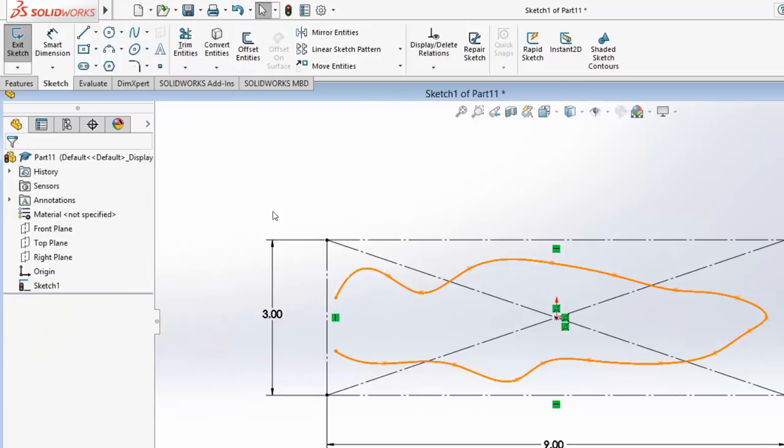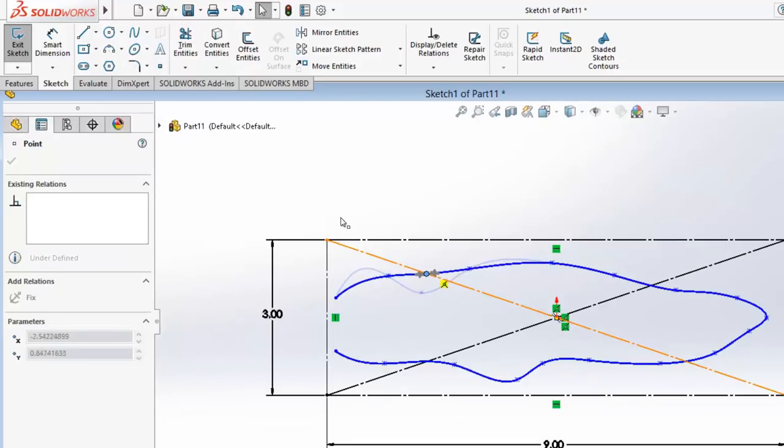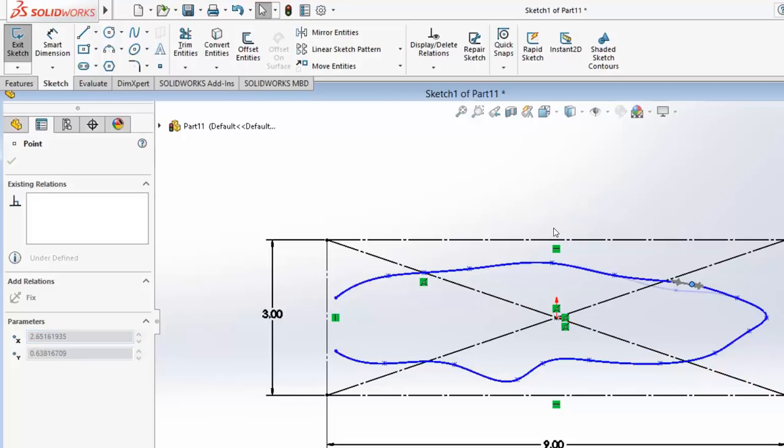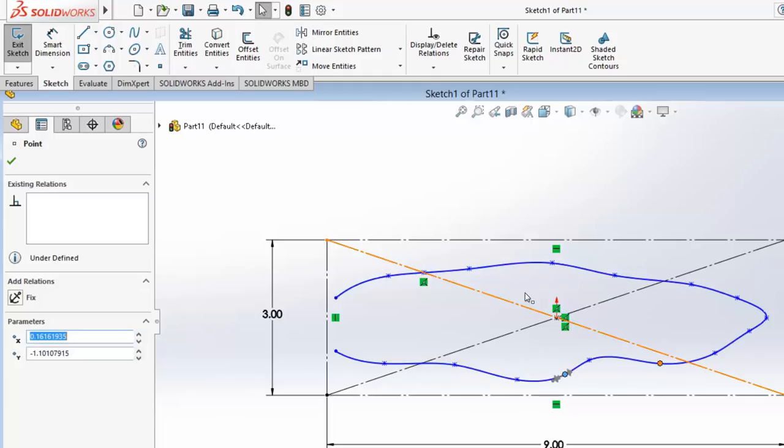So this fits inside of that rectangle. Here's the overall shape with the spline tool that I used right now. One thing that's really cool with this is that once you draw, if you decide, you know what, it's not exactly the way I want it, you can grab these nodes and stretch and shrink things accordingly until you get into the shape that you want.